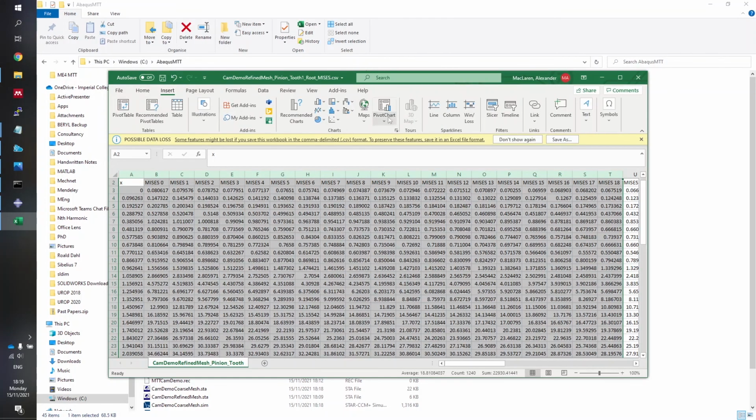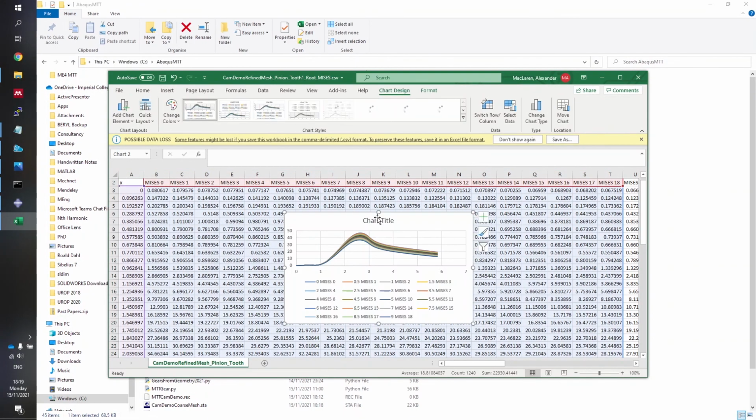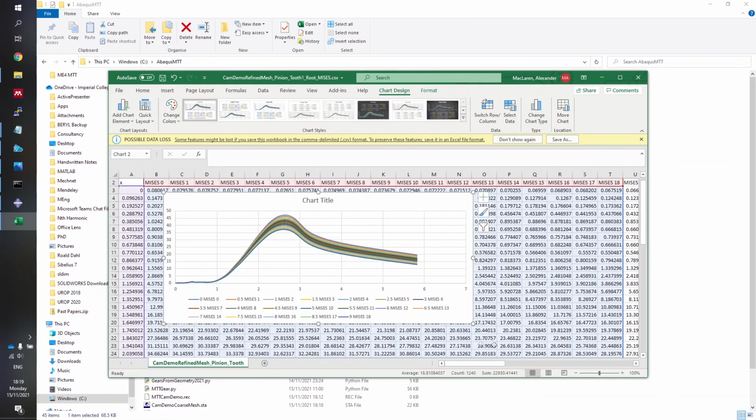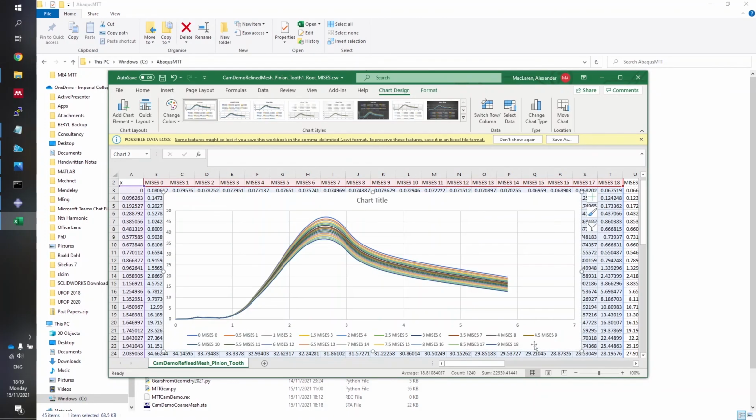And if we just do a small number, we can now see, looking from minimum radius to maximum radius, what the bending stress in the tooth root looks like. So this first millimeter is the dead end mark, presumably, and then we get a large stress concentration at the root fillet, which tails off down the cantilever of the tooth.